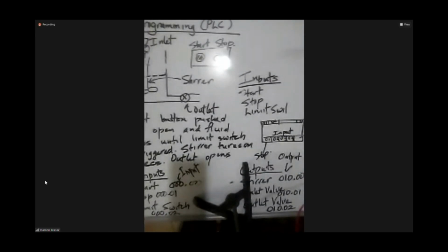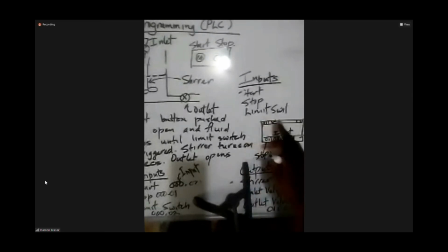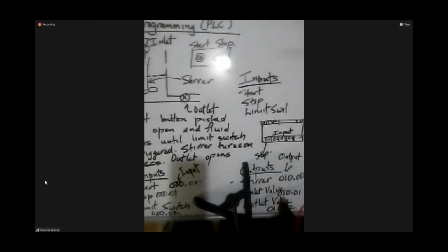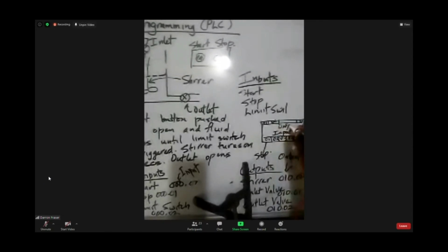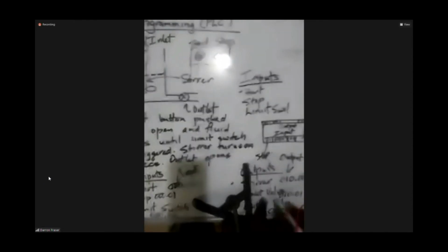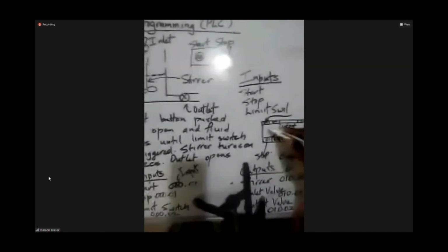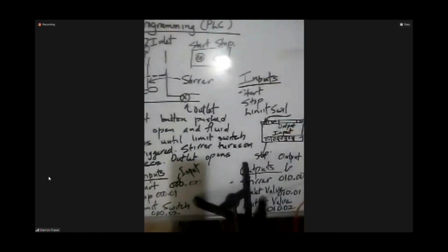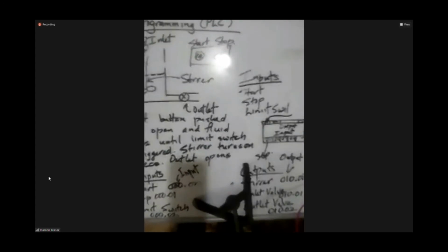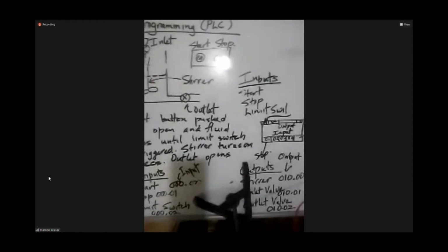So each of those slots, if you decide to name this, 000 is on it. But let's say you give the inlet valve the address 010. It is expected that you are going to connect to the output side, and the inlet valve must be connected here. So the wire must connect to the PLC at 01. So you don't have anything to do with binary.